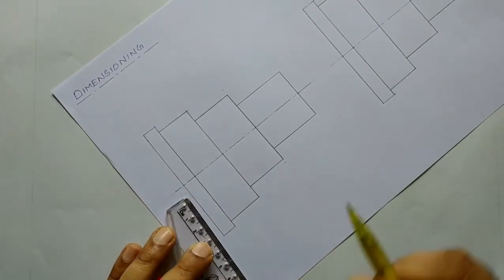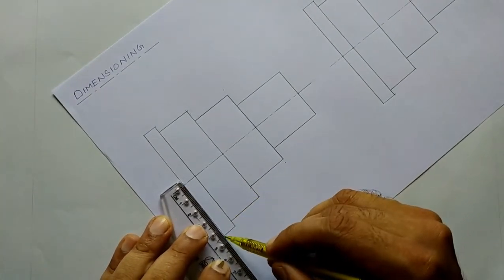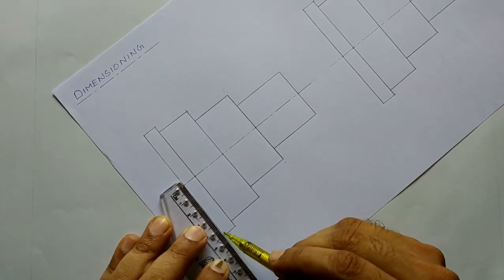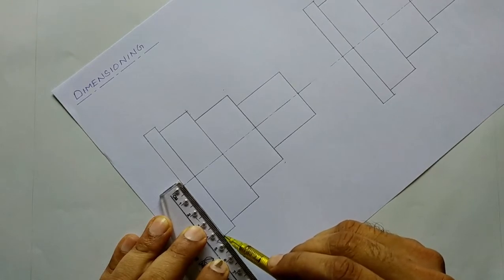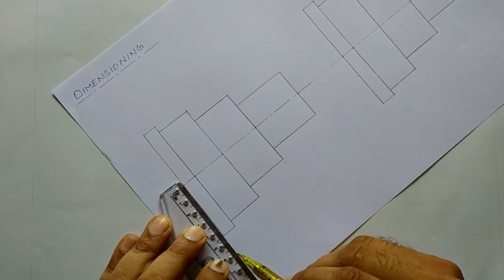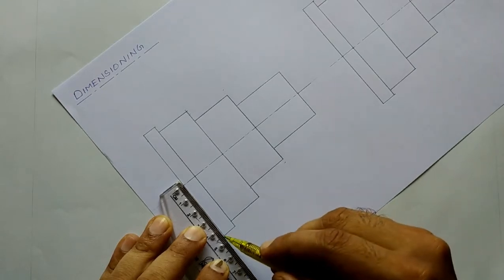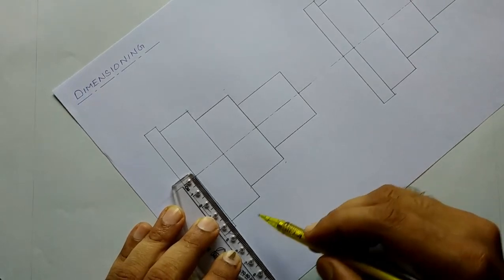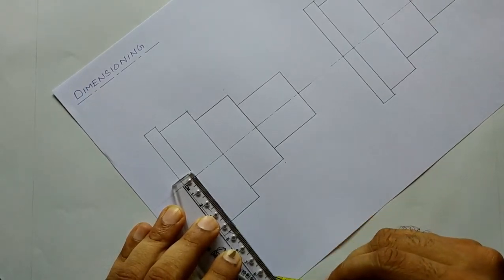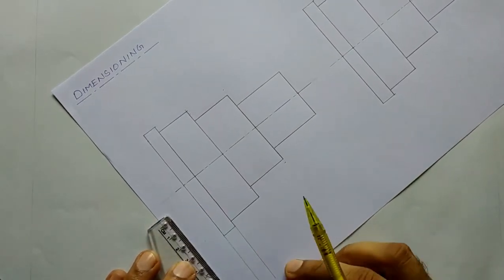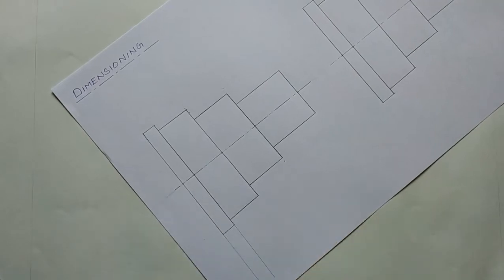So here, this line or this thickness, this one is 10 mm. In order to mark this dimension as 10 mm, I am extending a small thin line from this end, and this line is known as a projection line. Okay, this one is known as a projection line. I am drawing a continuous thin line. This is a projection line. Again, I am drawing another thin line. This is also a projection line. Okay, so this distance is 10 mm.